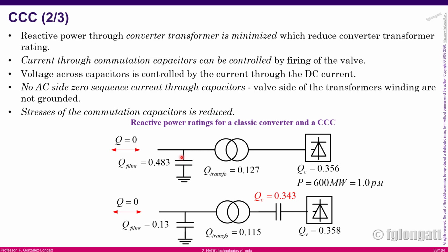But now what we are doing is one step forward in the use of those modern converters, LCC, trying to keep pushing the use of LCC. Instead of keeping a line between the transformer and the converter bridge, we install here a series capacitor.